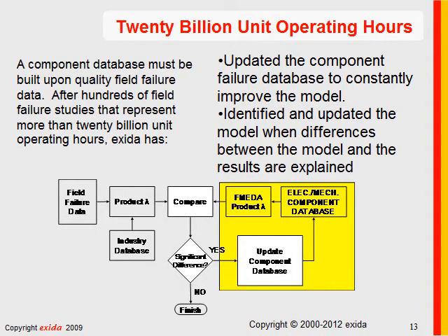We've calibrated the component database based on hundreds of field failure studies, primarily from petrochemical and power, some nuclear, and we update the component database virtually 100 times over the last 12 years, and we found that the current FMEDA failure rates match product failure rates from the field in the process industries, in low-demand applications, very nicely.